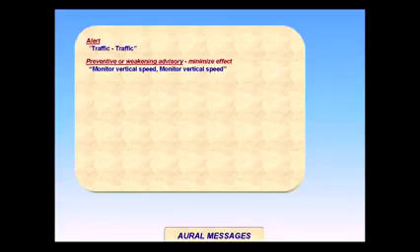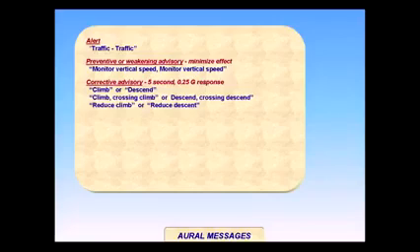"Climb, climb, climb," or "descend, descend, descend." Set vertical speed to the area shown in green on the VSI. Maneuver at 1,500 to 2,000 feet per minute within 5 seconds to avoid the red prohibited area on the VSI tape.